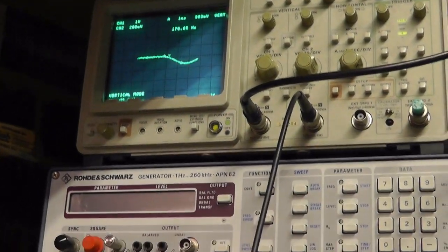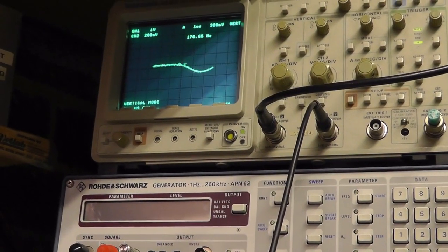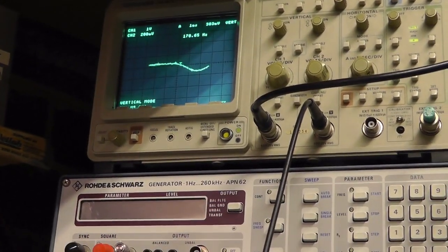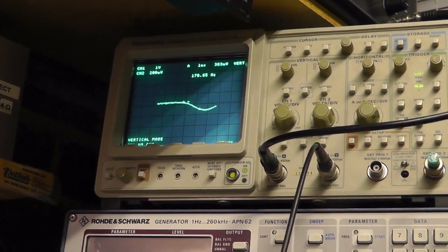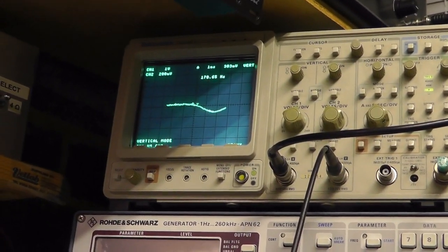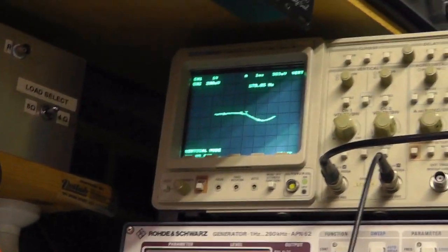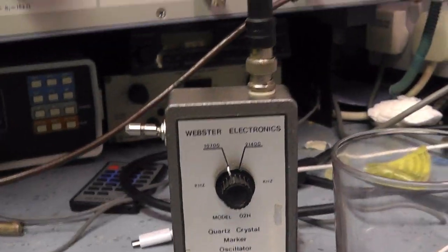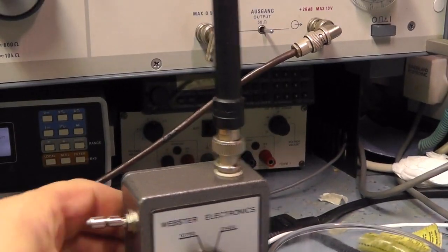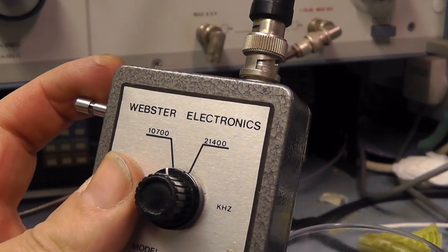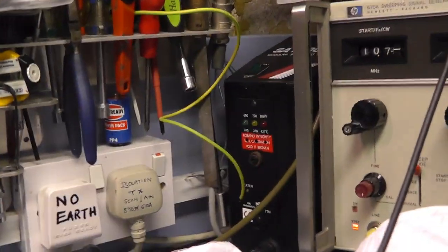Now, what I'm going to do is I'm going to run through the procedure. The other thing that's really useful, unless you could be absolutely sure you know where you are, is it's nice to know exactly where your 10.7 megahertz center frequency is, because you want that in the center of the S curve, and I'll try and show that in a moment. What I use, and I bought this on eBay, this little Webster Electronics marker generator. It's a great little thing, very straightforward crystal oscillator, but all I do is I put that near the radio, and I'll turn this, let me set the scope up so you can see.